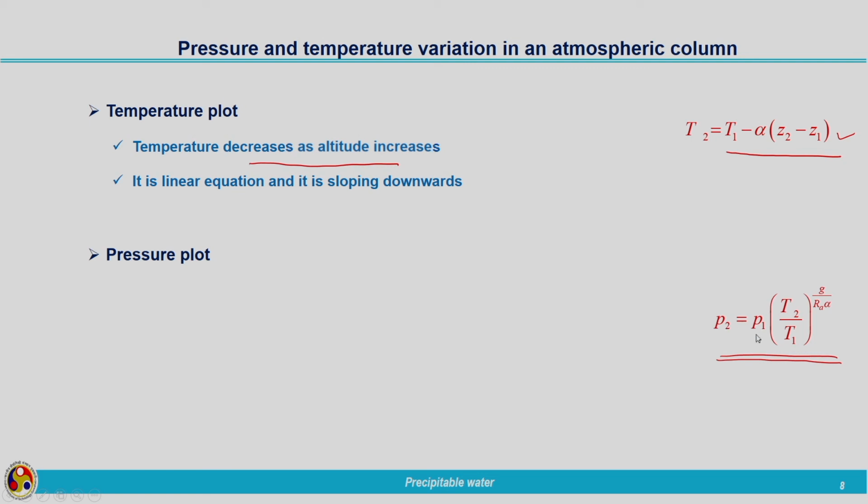So, P1 multiplied by T2 divided by T1. We have already seen from this relationship that T2 is lower than T1. So, here the numerator is T2, T2 divided by T1 to the power of some quantity, multiplied with P1, you will get the value corresponding to P2. So, definitely P2 also will be less than that of P1.